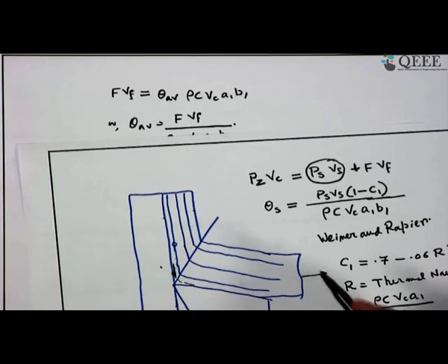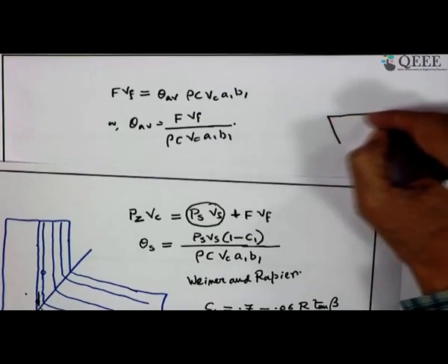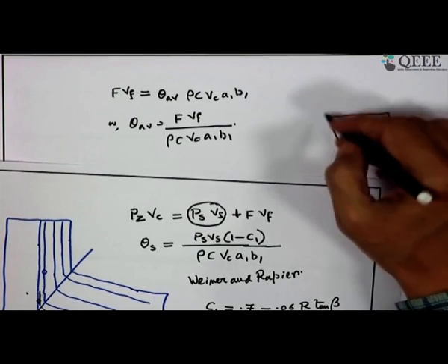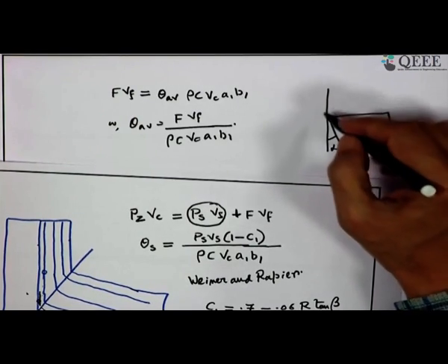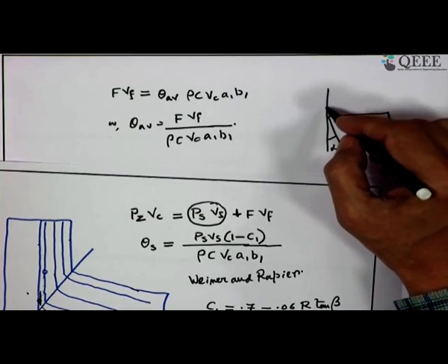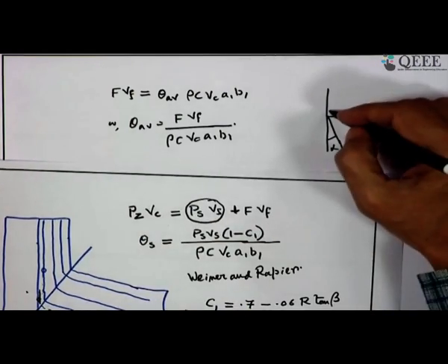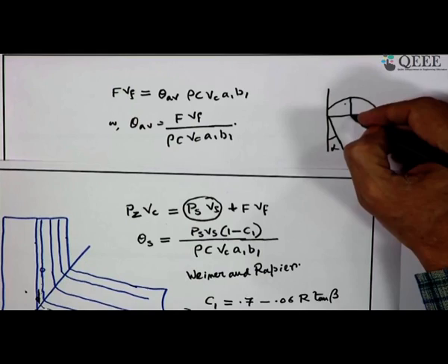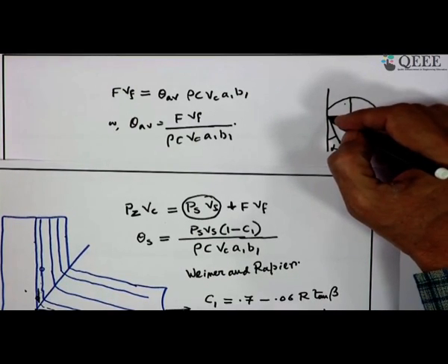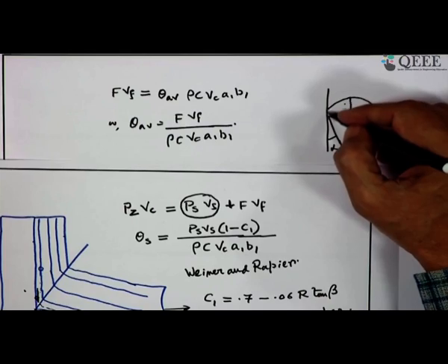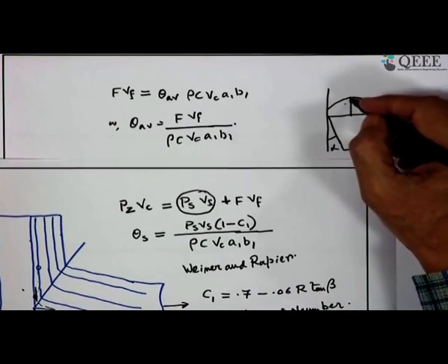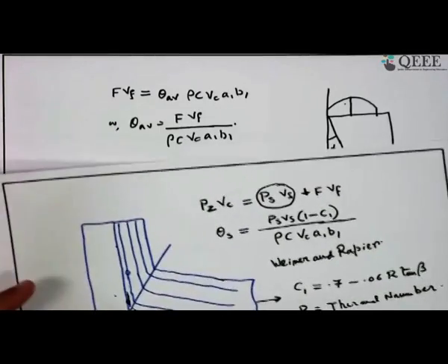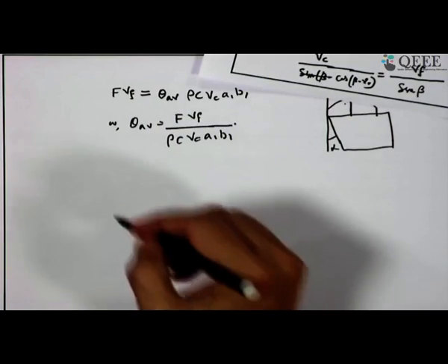So, if you have a temperature plot, with the rake surface of the tool and this one the clearance surface, the profile of the temperature on the rake face will be something like this. The highest temperature is a little away from the cutting edge because of the rapid conduction of heat. So, from this point of view, there is further consideration of how to get this.